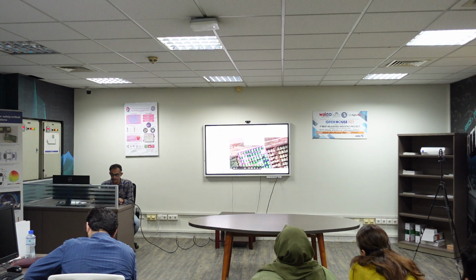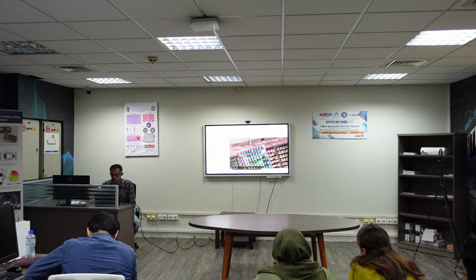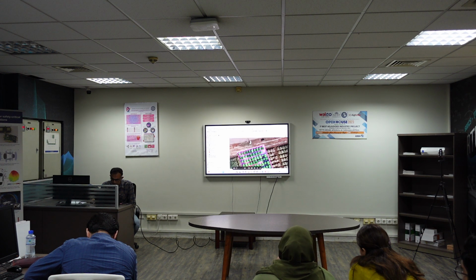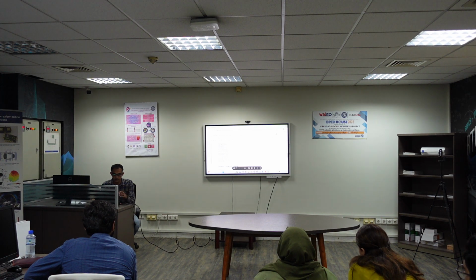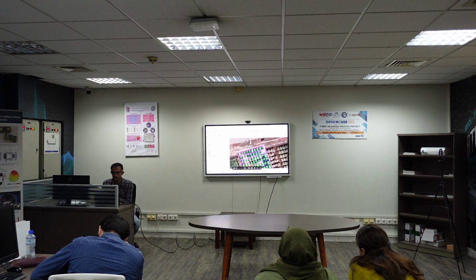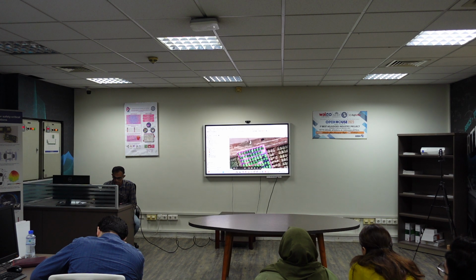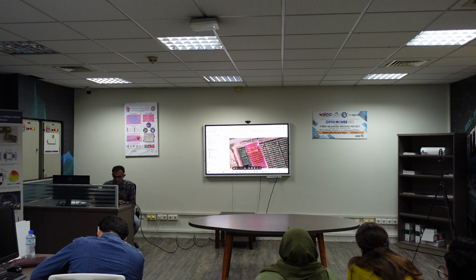And the next thing is the orientation. Now you have seen that once we have used the grid layout, it does not care what orientation was required. But here I have tried to cater for that as well. So for example, the orientation that this plot has is 72 degrees east. So you can just plug in 71 or 72 plus 90, because you can see this is oriented in a rectangular fashion. So you just have to add the 90 degrees and you will come up with this. You just plug in the values and ultimately you will generate a block. So let me show you this. Now you can see that it quite aligns.